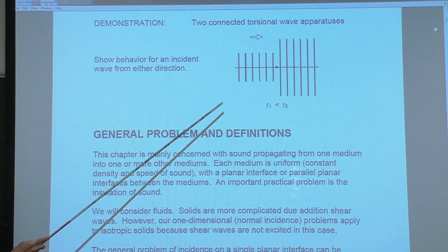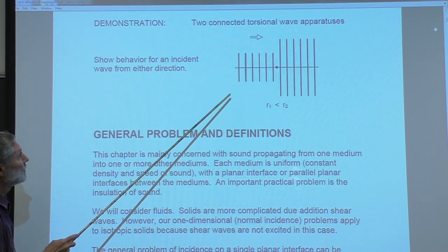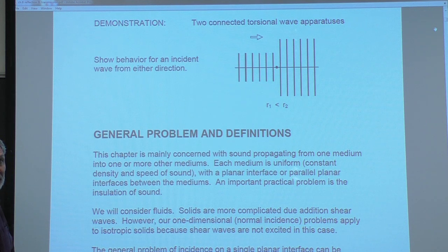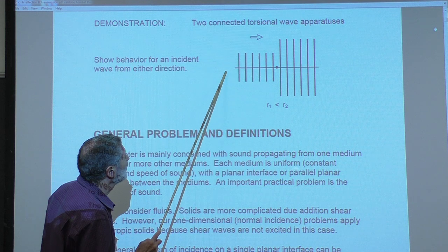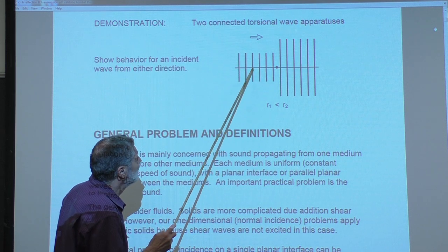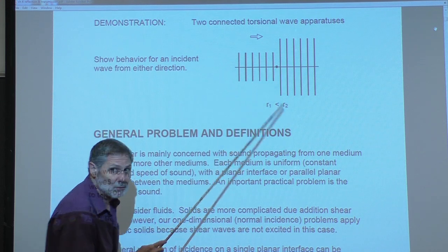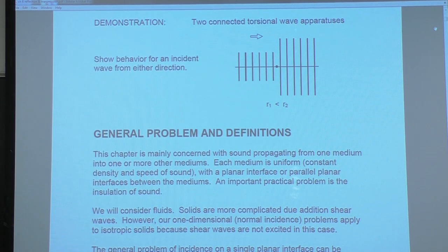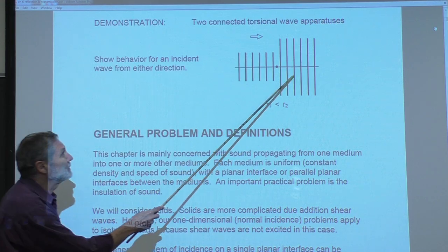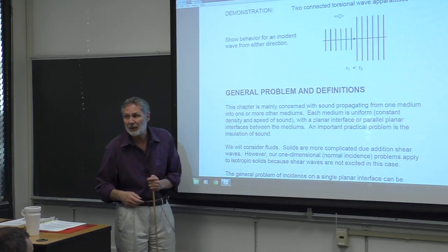And then the inertias are different, right? So there will definitely be an impedance mismatch here, and sure enough, you saw reflections. However, you can imagine that as a wave is traveling here, you can imagine matching the impedance here. What's one way of doing it so that there are no reflections? You have greater inertia here, right? You've got to keep the product the same.